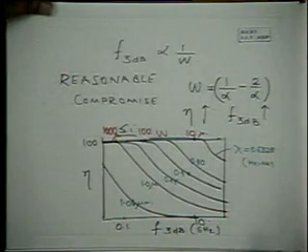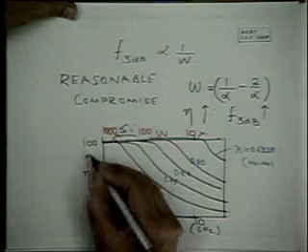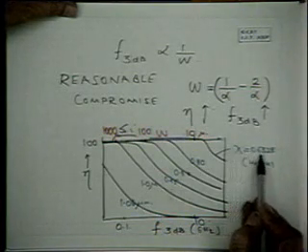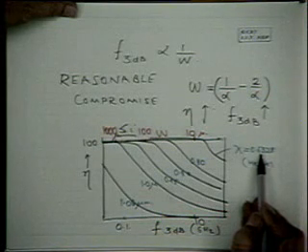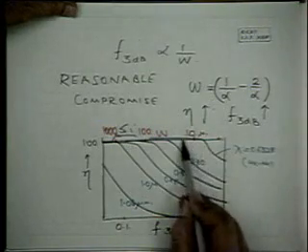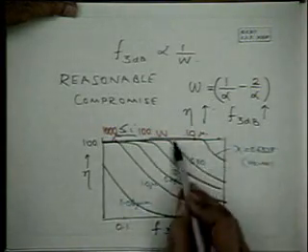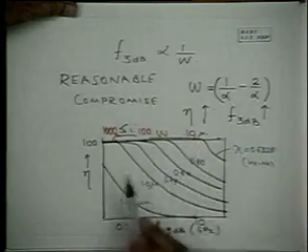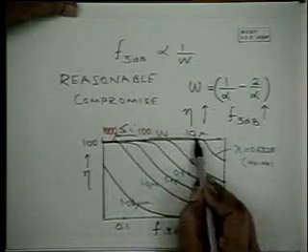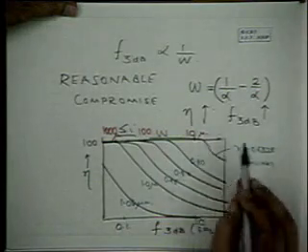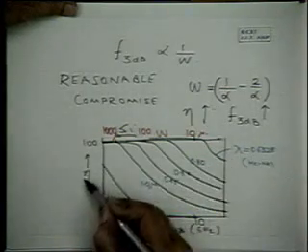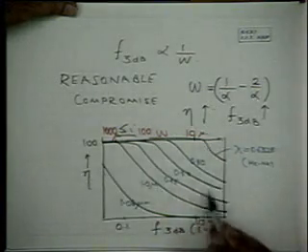So what does this graph tell us? That for a given p-i-n diode, if we have, say, lambda at 0.6328, then alpha is very large. If alpha is very large for a given width W of the intrinsic layer, the quantum efficiency remains large up to a high frequency, and the frequency response is also high.